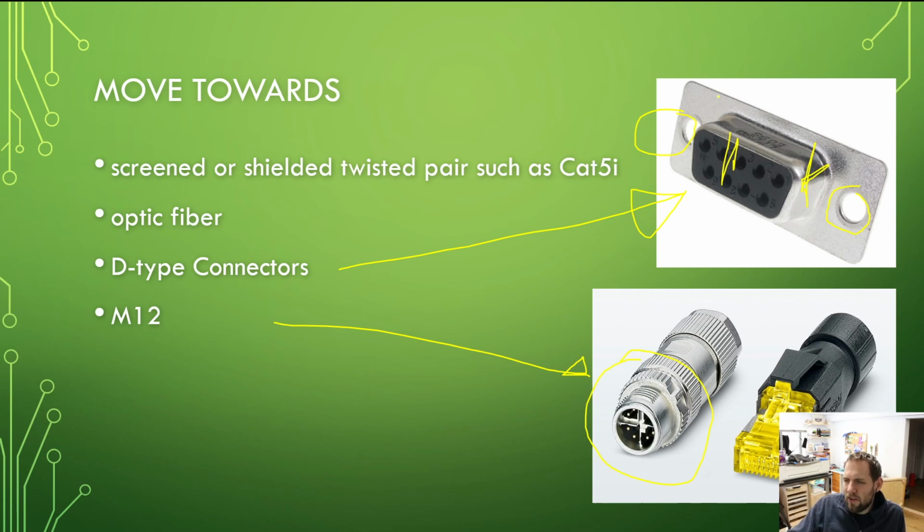And again, you can keep your shielding because this is metal, and you'd have metal on the other one, so you can still have RF protection going on those DB9s. Obviously, down here on these M12s, you have metal connection. You're going to screw onto it, so you have good shielding there. For M12 connectors with industrial applications for Ethernet, we are going to use the 8-pole variety. So the poles would be the number of pins going on in here. So this one would have 8 of them. And there are ones that have more or less. All right, if you ever look at some military connectors, they're like big honking circles, and there's like 20 or 30 different pins in there that allows you to connect things very securely with screw-in threads and those types of things. So just again, something to keep in the back of your mind.